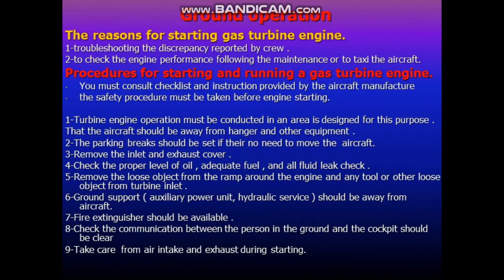The reasons for starting a gas turbine engine. The first one, troubleshooting the discrepancy reported by the crew. As a maintenance technician, you will often operate a gas turbine engine for troubleshooting that was reported by the flight crew, which might require you to operate the engine to attempt to duplicate and analyze the fault.